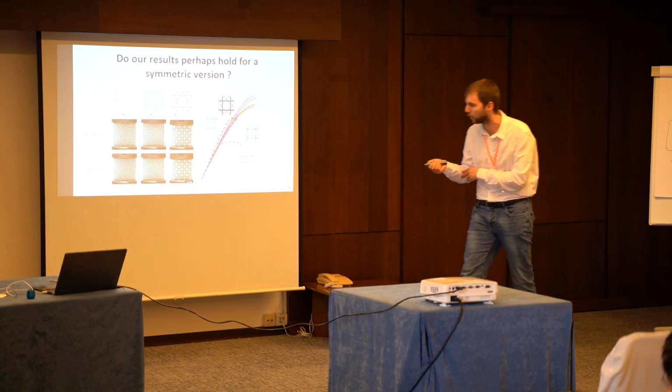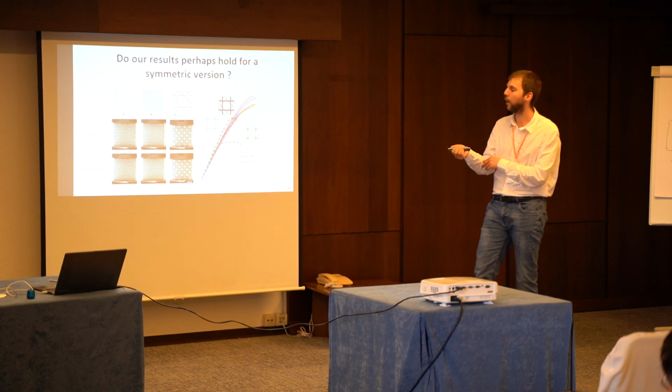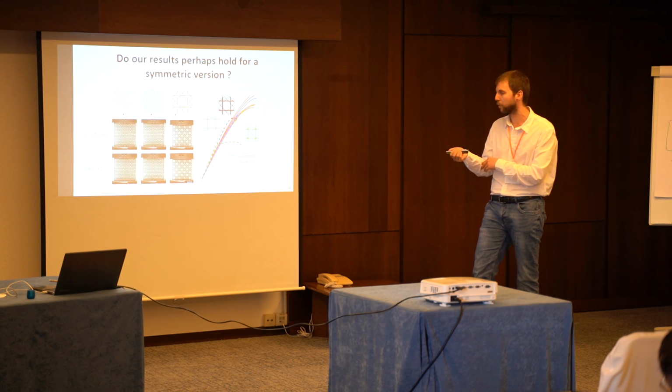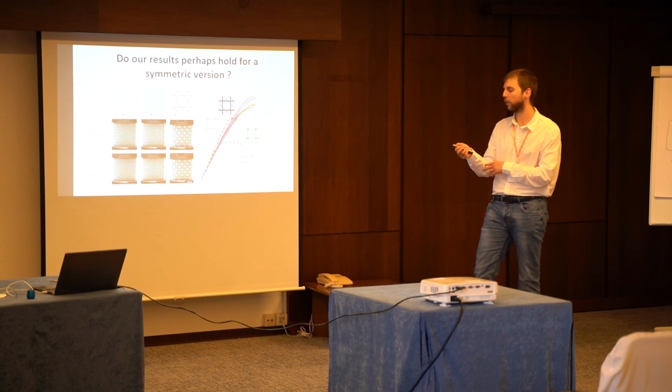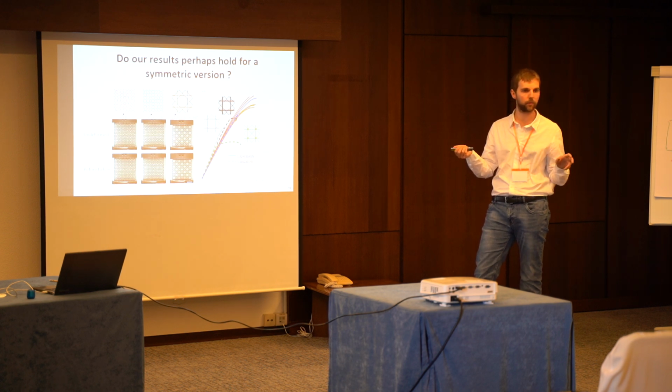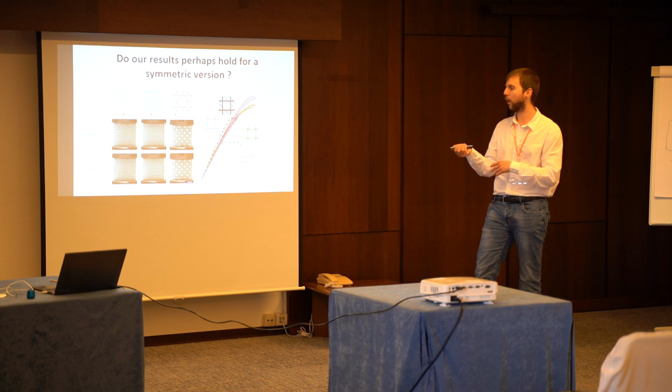you maybe can't see, it's small here, that the displacement of the structures is not visible compared to the sponge B, which means that, being optimized for buckling, they are less prone to buckle than the sponge design. Therefore, their effective buckling strength is almost the same as the effective fracture strength.